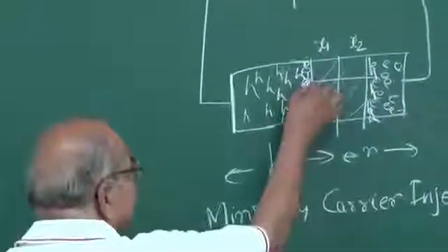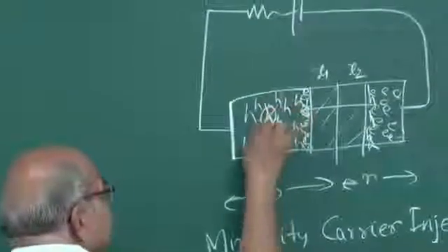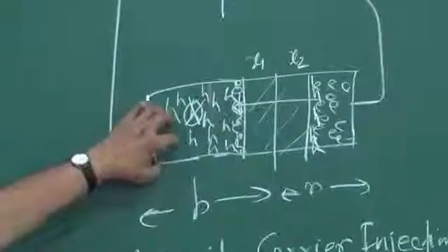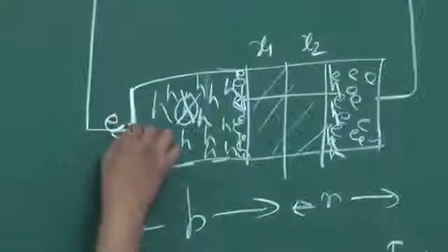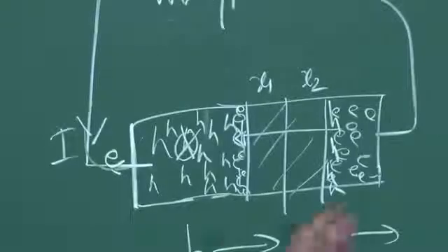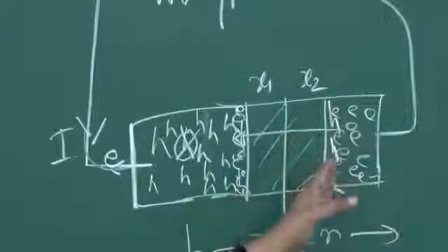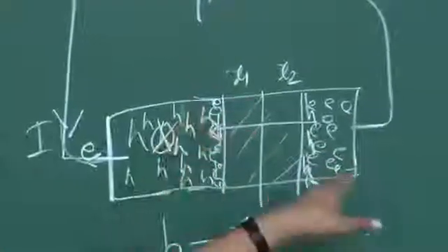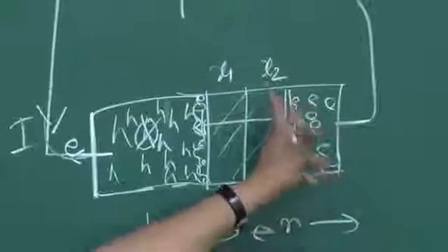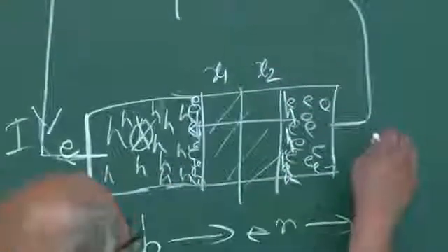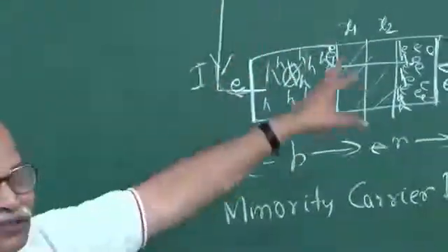All that chemistry inside the cell is for that, to maintain a potential difference. And so if this electron combines with a hole, and this hole goes out, negative charge appears, so one electron has to be withdrawn. So one electron is withdrawn at this contact, and then the electron goes this way, the current goes this way. Similar is the story on this side also. The holes have a large concentration here at the edge of the depletion layer, and towards the other contact they have to diffuse, and during diffusion they can combine with an electron, and one electron can go. And if one electron goes from there, once again negative charge goes, and therefore this circuit will supply an electron through this contact here to compensate that. So that is how the current goes.